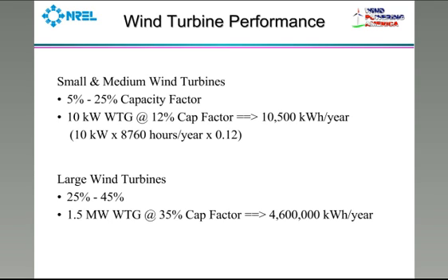And finally, people put them in for a lot more than just pure economic reasons. And so they're often put in sites that don't have a lot of wind, unfortunately. So you see a fair number of installations where the capacity factor does drop below 10%. So what can you expect from a small wind turbine? Probably 12% is from this example.